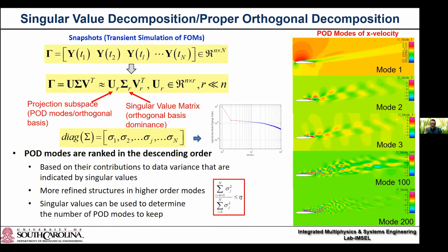The reason we want to update the POD modes is that when new streaming data come into the picture, your POD modes will shift, the subspace of the solution will shift. Then we want to update that space of the solution, which is deterministic, by the way. So that's the reason why we introduce the update here. Again, to answer your question, this update is to address the shift in the solution subspace rather than for uncertainty.